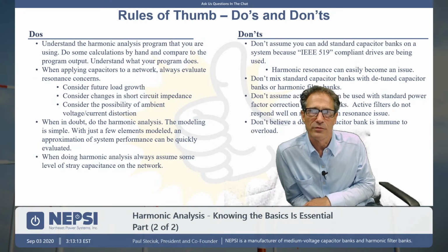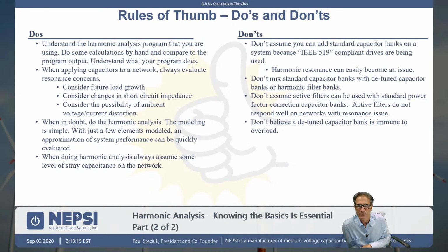So just to go through some do's and don'ts, some things that we picked up in the presentation. Understand the harmonic analysis program that you're using. Going through the analysis that I just did is very important. If you can't do it on paper, you're not going to really understand harmonic analysis. So we recommend that you take the time, develop a very simple system, perhaps even the one that we used in this presentation, and replicate it in your harmonic analysis program, whether it's ETAP, CYME, VHARM, PSSU, EasyPower, it doesn't matter. Just do it.